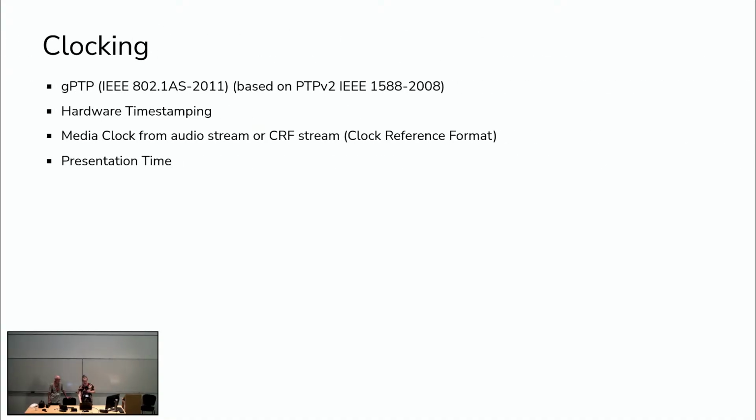But that's not the only spec. For clocking, it uses gPTP, a derived standard from PTP version 2. For this, usually you want to use hardware timestamping. PTP is used for the clock, but you still need a media clock for synchronizing the devices. It's like a word clock.